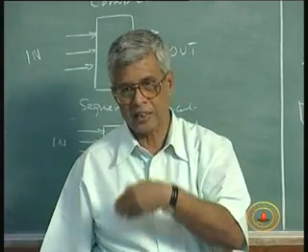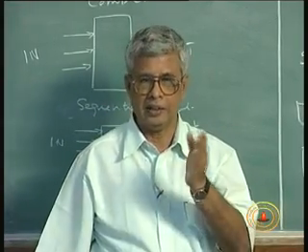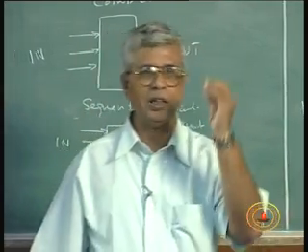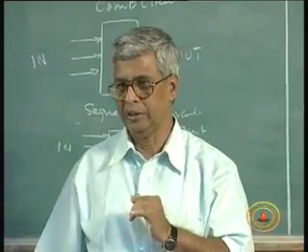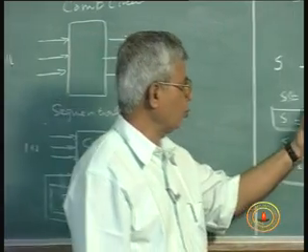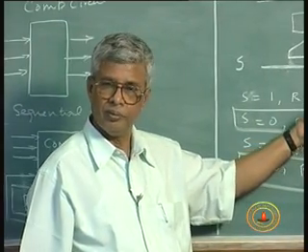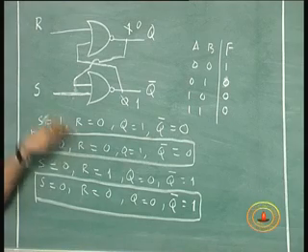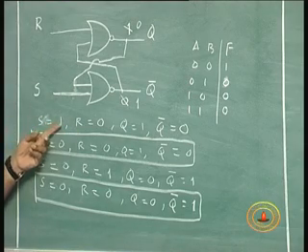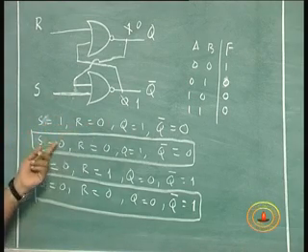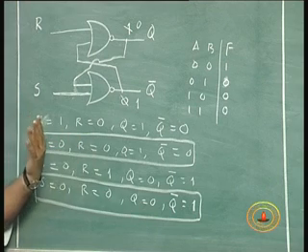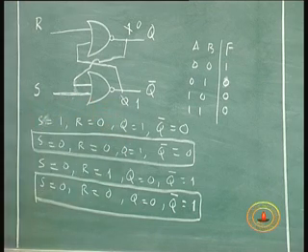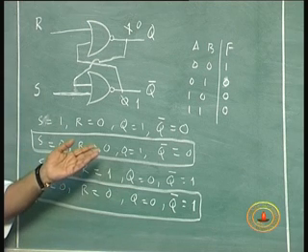It is erased and written over. I can change it and say, no, what I said yesterday was wrong, this is the new information. Then you will try to hold on to that new information. So, the information which was put was 1, 0, and after this we removed that excitation, made it 0, 0, both inputs are 0, the output remained 1, 0. The memory retained the information.